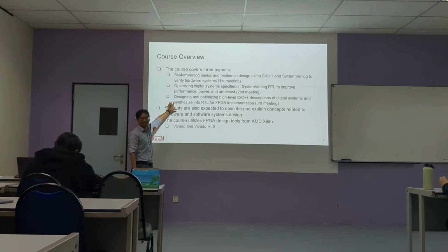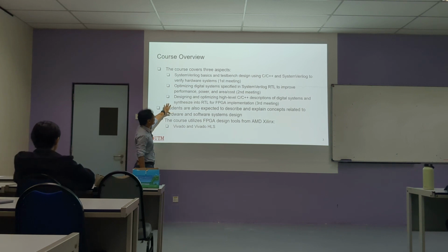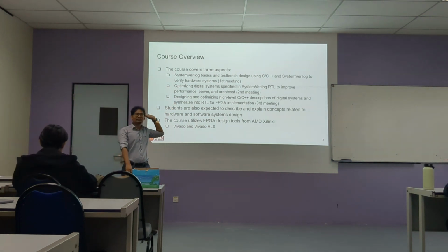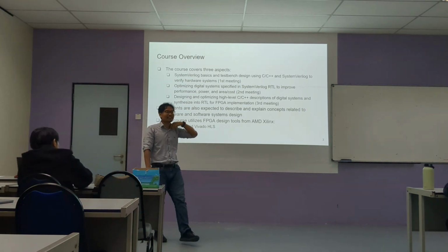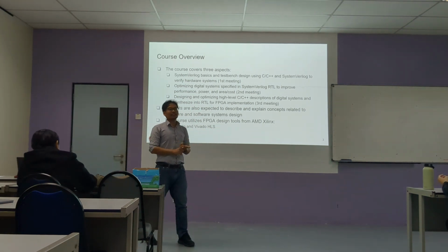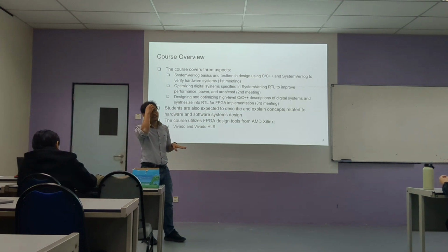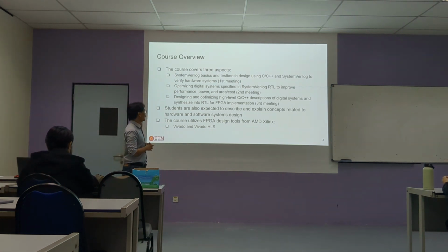Right, so we cover it in the undergraduate, and I believe that most universities don't cover HLS methodology. Or perhaps some other universities have covered HLS. HLS is converting from C to Verilog. Okay, you write the program in C, and then you generate your system Verilog code, instead of writing the RTL manually.